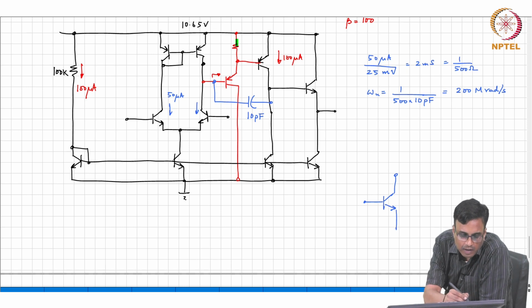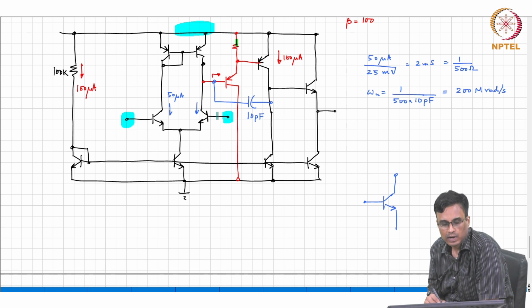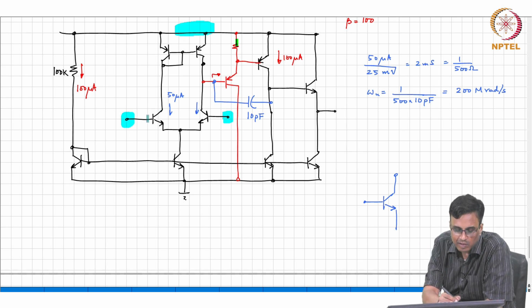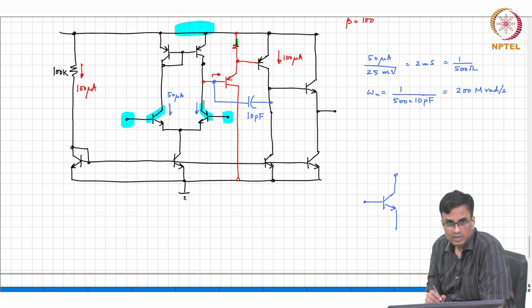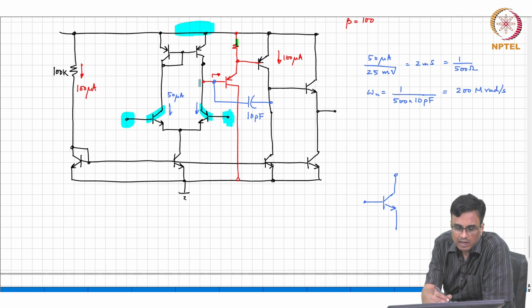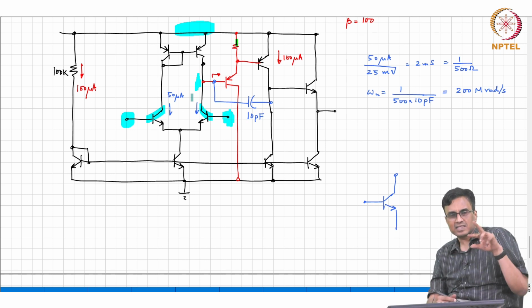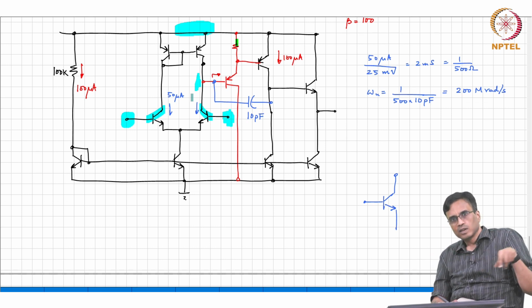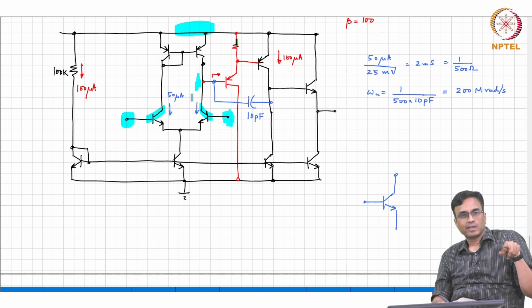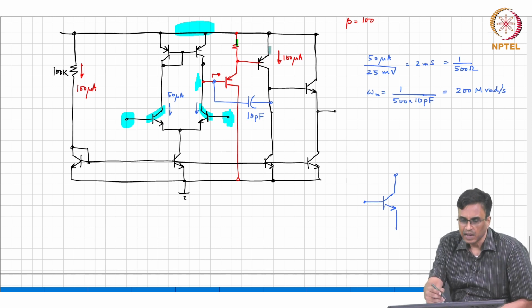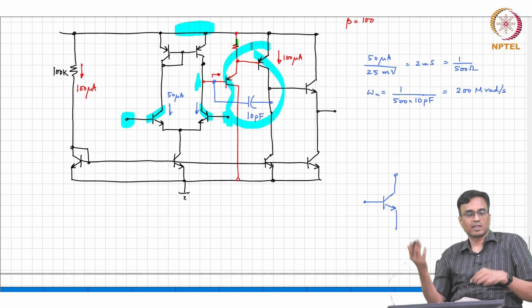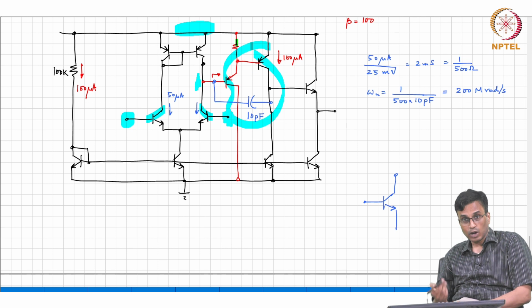If the supply voltage is lower than the common mode voltage of the input, so the input common mode is greater than supply, what happens? These transistors will become saturated. So, whatever happens here, the same thing will happen here. What is supposed to be negative feedback, you had arranged the signs of the op amp so that there is overall negative feedback. Now, the input transistors are saturated and the negative feedback has become positive feedback, and there is enough gain in these transistors to cause the loop gain to be greater than 1, but now with positive feedback.